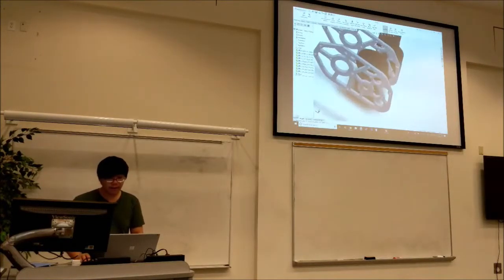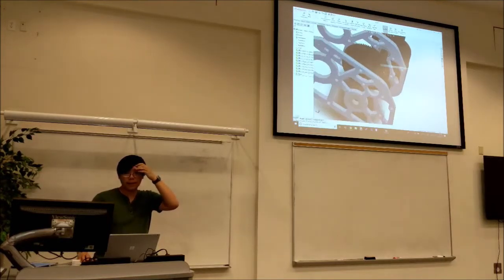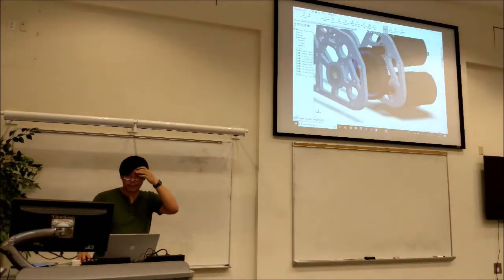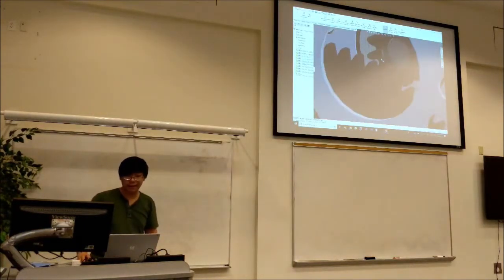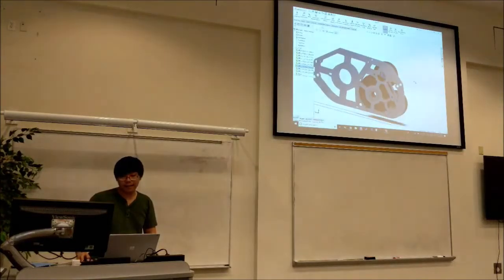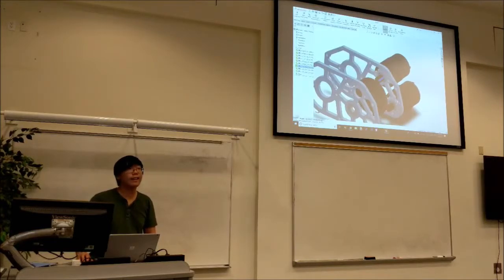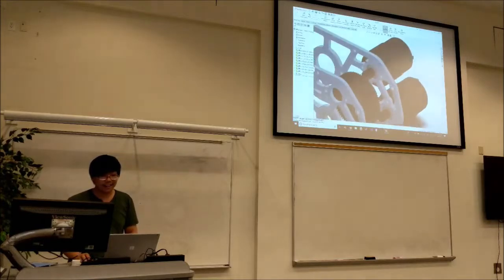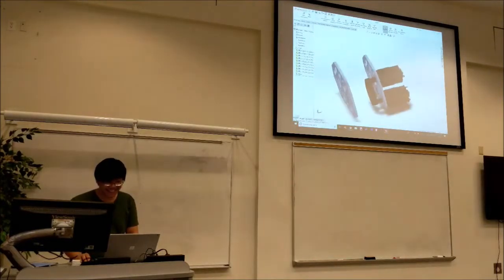So you can see, because we did that initial sketch and modeled the gears as this pitch circle, now that we put this gear in, it meshes perfectly with this other gear. And that's with the 3-thou tolerance? Yeah. That's not something we developed, that's just something that has been historically done in FRC for gearboxes. And if it works for Cheesy Poofs, it works for me.